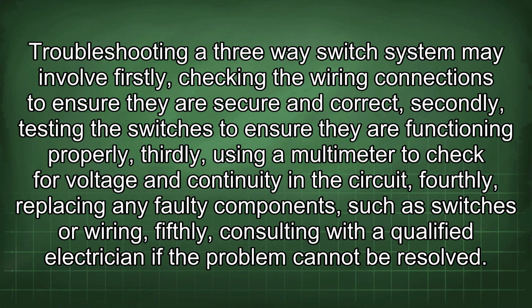Thirdly, using a multimeter to check for voltage and continuity in the circuit. Fourthly, replacing any faulty components such as switches or wiring. Fifthly, consulting with a qualified electrician if the problem cannot be resolved.